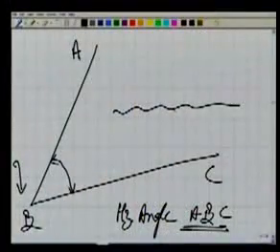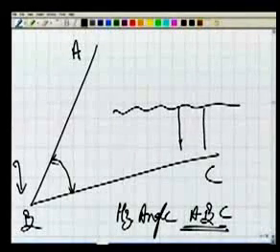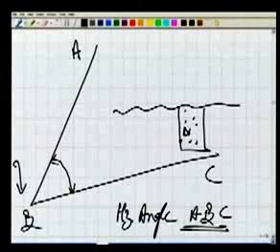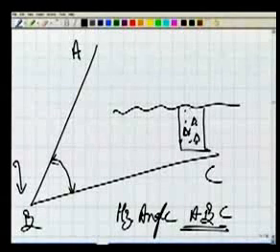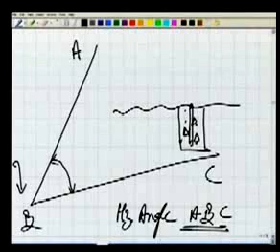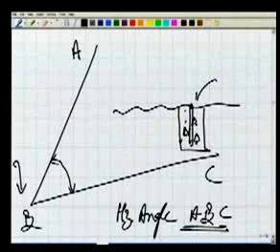Well, the traverse stations, or survey stations, are mostly decided on the ground as particular points. Generally, we will put a concrete block, and in this concrete block there is an iron nail which marks the center of the station.